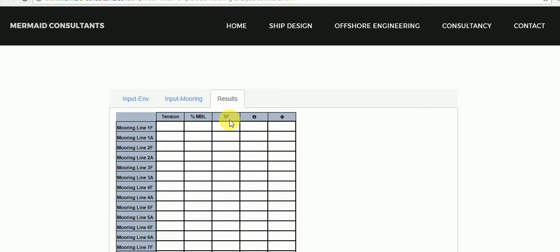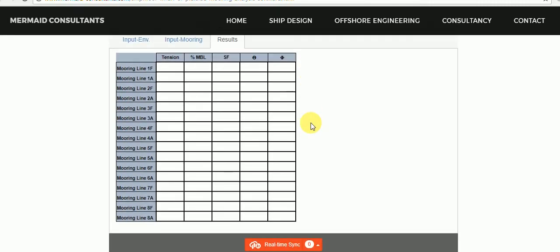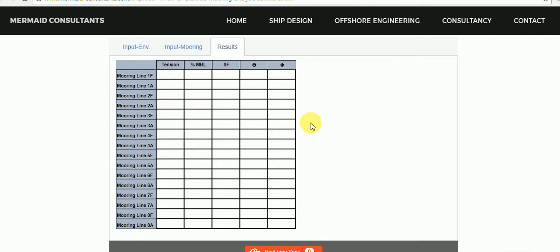Auto-generation of wind or wave capability rosette. Option to lock vessel, berth data. Comprehensive rope and fender property database. Auto or manual pre-tension to set up mooring and optimize arrangement. Ship-to-ship option for side-by-side mooring.